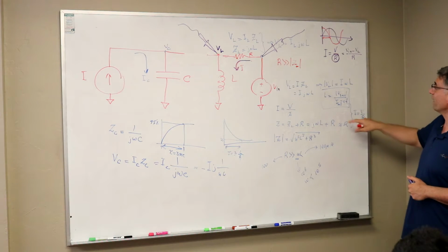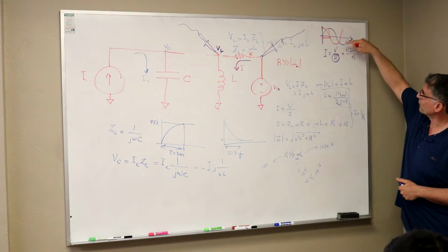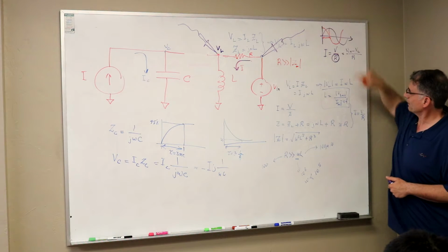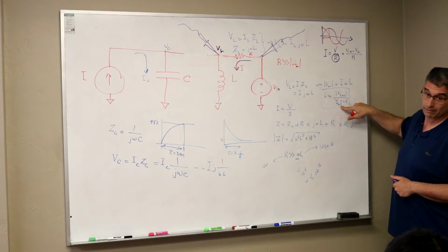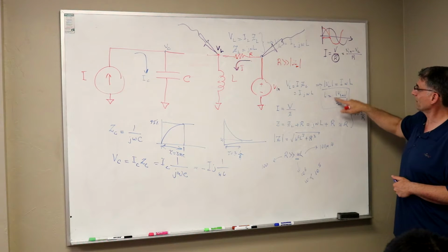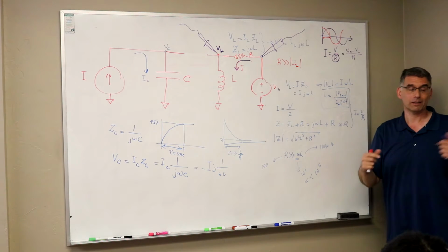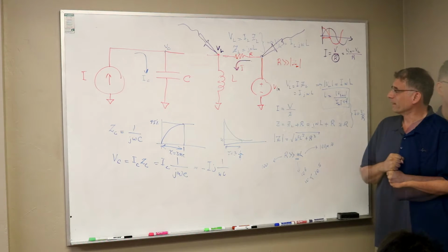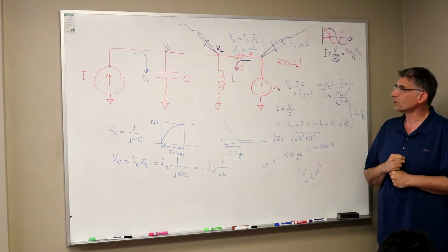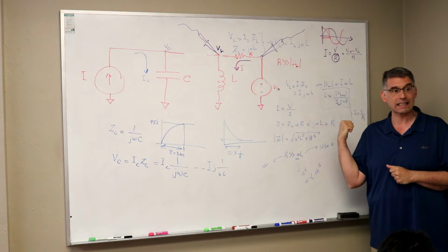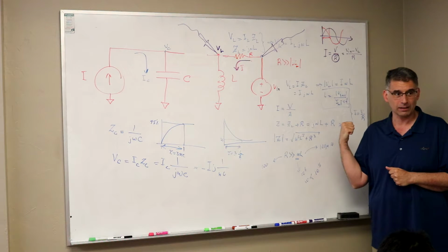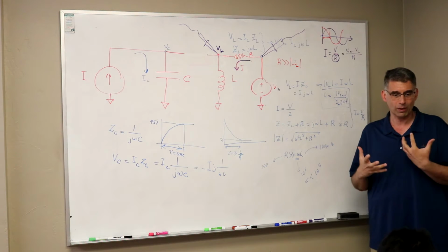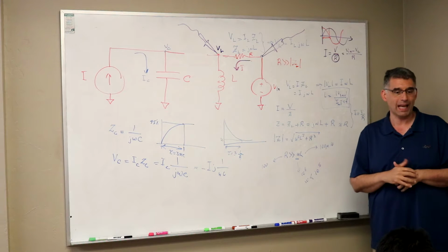And so then, to find out, you measure VL at the max, you measure I at the max, you plug it into this equation, and that gives you the inductance. Okay, so do I need to go over this again, or are you guys good? Maybe we should just do it. Let's just do it, and then if there are questions, we'll answer them.